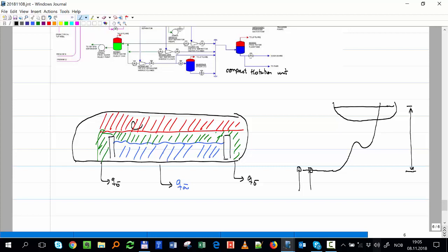You can be creating a lot of back pressure on the well. So just like in a well, you send out a gas line and inject it at the base of the riser to reduce the column and the pressure drop. It's like applying a gas lift on a pipe. So this is riser base gas lift.